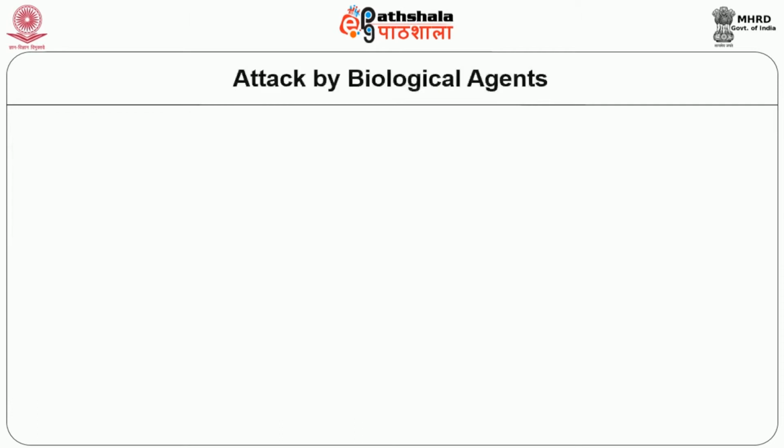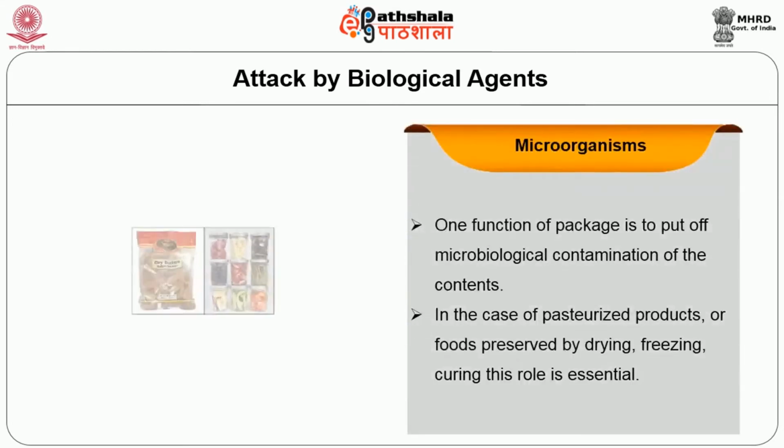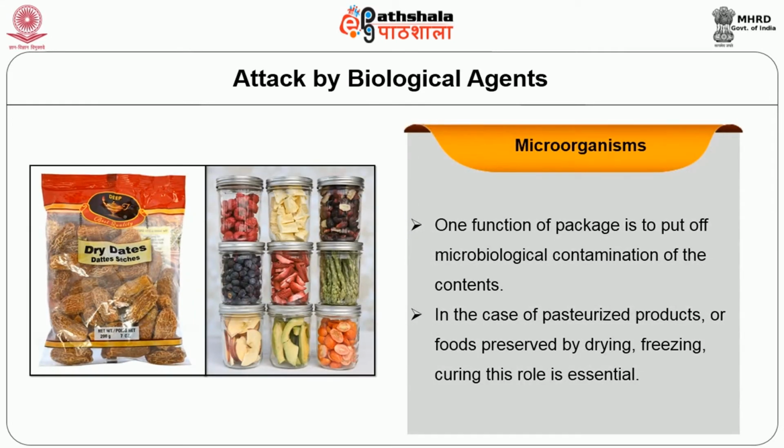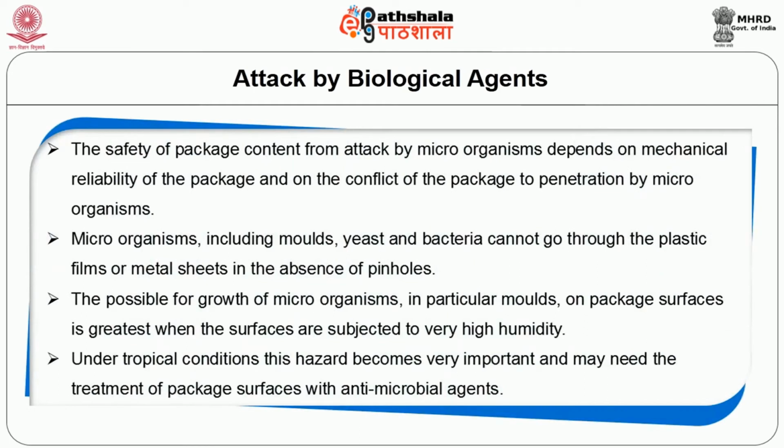Next is attack by biological agents. Under that, first one is microorganisms. One function of the package is to prevent microbiological contamination of the contents. In the case of pasteurized products or foods preserved by drying, freezing, or curing, this role is essential. The safety of packaged content from attack by microorganisms depends on the mechanical reliability of the package and on the resistance of the package to penetration by microorganisms.